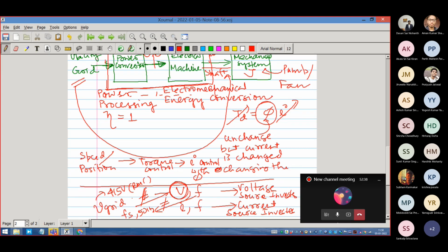meaning that not only should it reach the torque that we desire and the speed we desire, but with what transients is it reaching it? Is it reaching it very fast? Is it reaching it without much overshoot? Is the control system stable? Is it oscillating? All those issues will be judged in electric drive systems. An electric drive system, good or bad, will be judged by this kind of performance criteria.